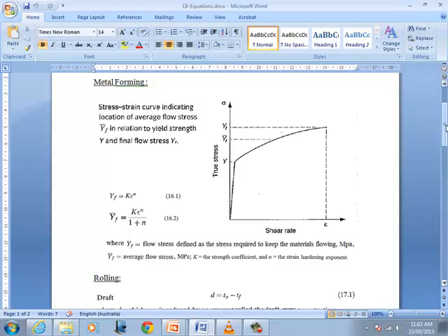And now we are talking about change of the shape of the material. If we are a design engineer, we are often interested in this part of the stress-strain curve, the linear part, which is the elastic part. We know that, right? What happens in the elastic part? If there is a change of shape, it's not permanent. You withdraw the load, it returns to the original shape and geometry, because it's within the elastic region.